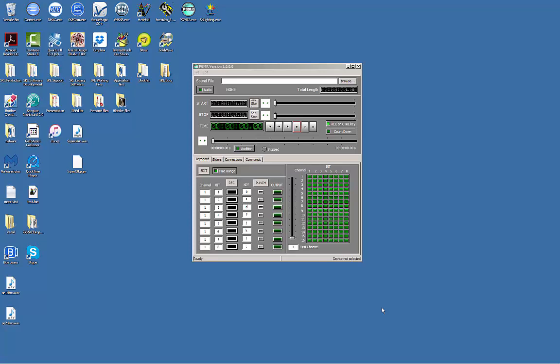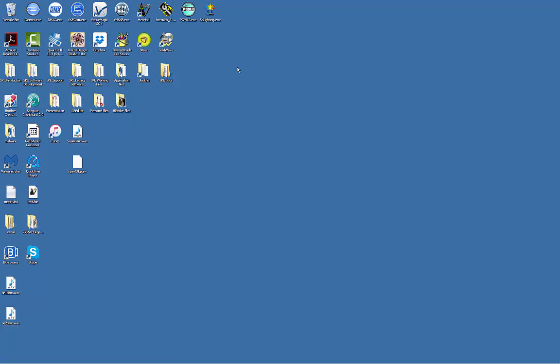The final output of the program can be either a project file, which you can load and save. It saves all the settings you last included, and also to export the final DMX binary wave file. It also allows for importing DMX binary wave file, and also you can FTP export the file upon saving it so that you can execute it directly in the unit.